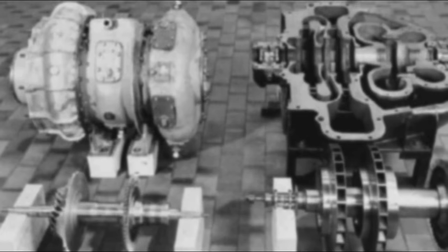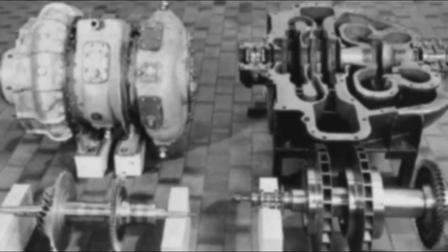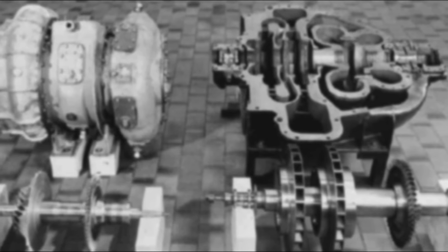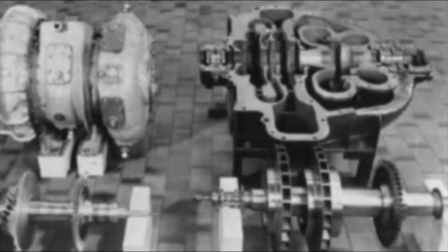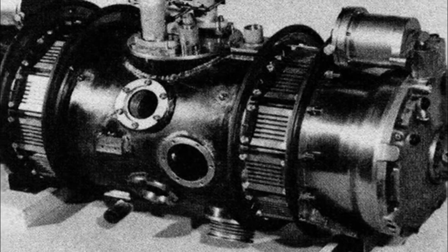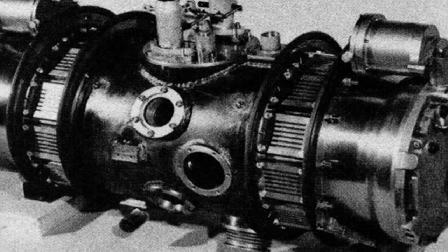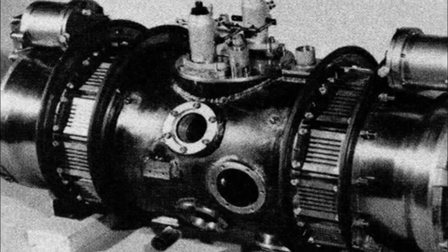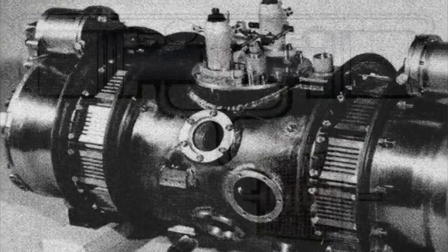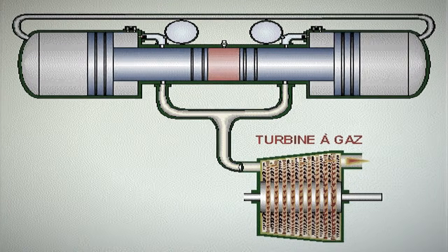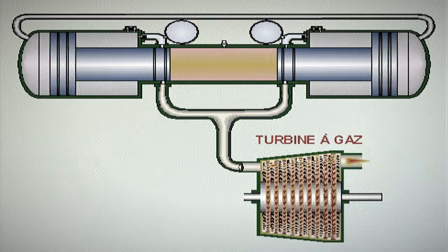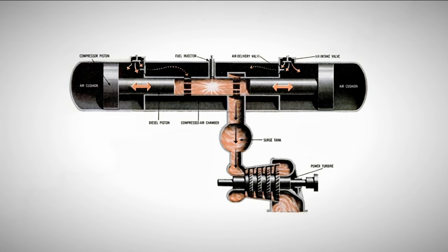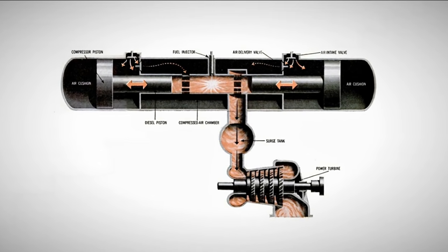The introduction of turbocharging on diesel engines with a power of about 300 horsepower made it possible to achieve a specific fuel consumption of up to 0.37 pounds per horsepower hour, while the combined turbo-piston engine of the Ford Typhoon tractor, with an overall efficiency of about 35%, demonstrated a specific fuel consumption of about 0.55 pounds per horsepower hour. As a result, the free-piston gas turbine engine never became a real competitor to either the diesel engine or the conventional gas turbine. In the early 1960s, further development of this technology for small vehicles was practically abandoned.